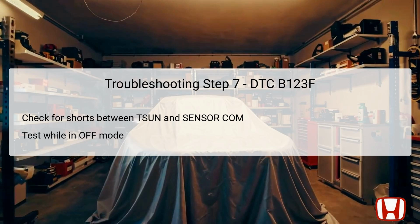If continuity is detected, it indicates there is a short between these two wires, necessitating immediate repair of the short. Conversely, if no continuity is evident, it confirms that both the T-Sun and sensor COM wires are functioning correctly, allowing you to move on to the next diagnostic step.